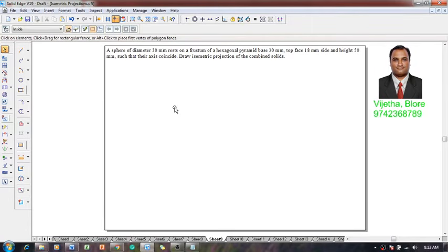I'm Vijay Tewardhan, and in this video session, I'm going to show you a problem on isometric projection. An example problem is like this: a sphere of diameter 30 millimeter rests on a frustum of a hexagonal pyramid, base 30 millimeter side, top face 18 millimeter side, and height 50 millimeter, such that their axes coincide. Draw the isometric projections of the combined solids.